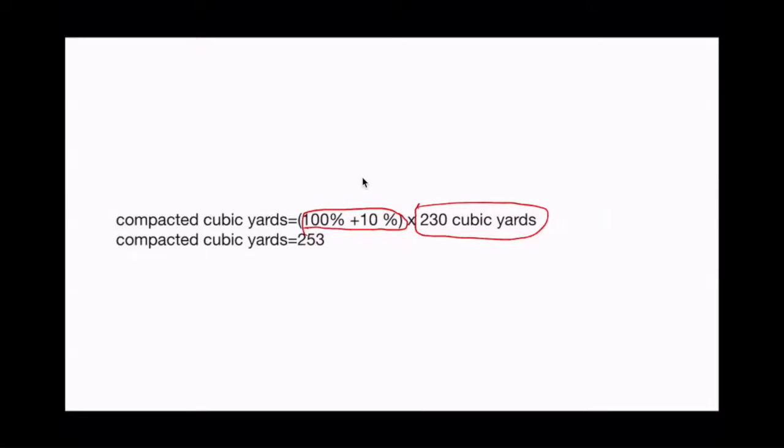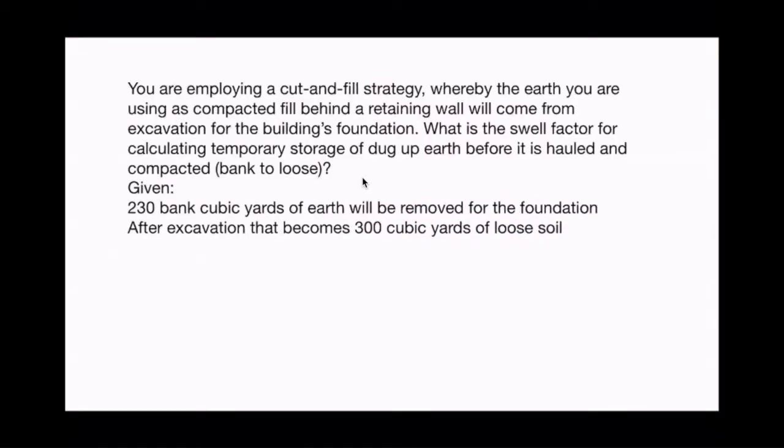As always, don't just look at that as a number. 253 is bigger than 230 by about 10%, and it's because we've dug it up and made it more loose, and then compacted it down, made it tighter, but not as tight as it was when we took it out of the ground. All right, now, this is your next problem.